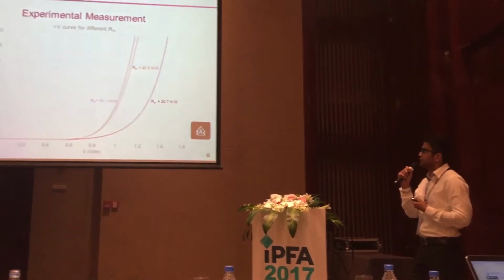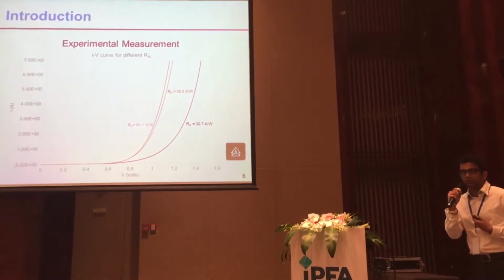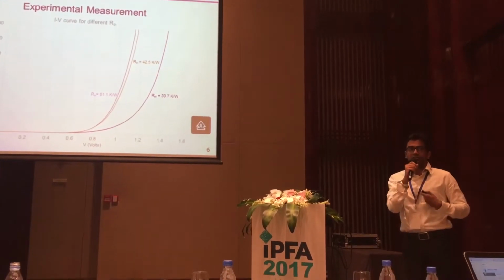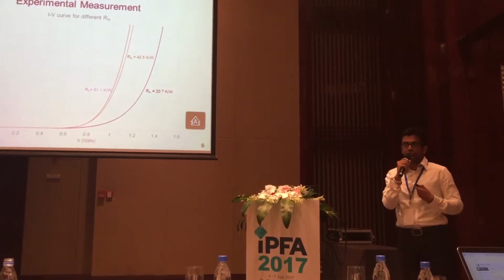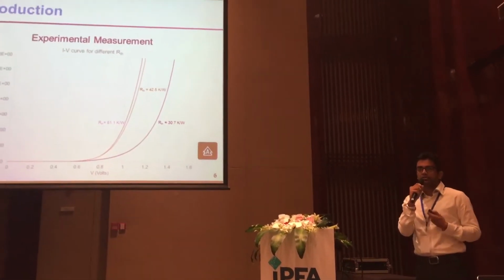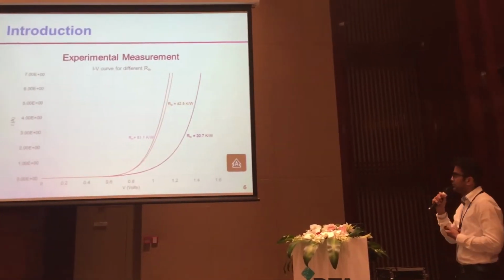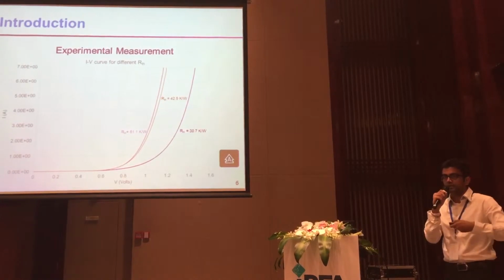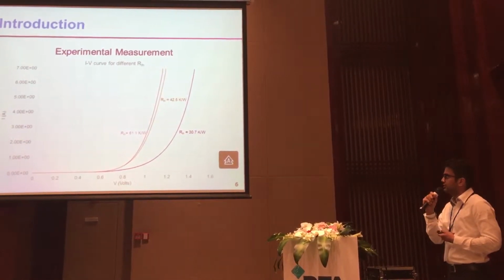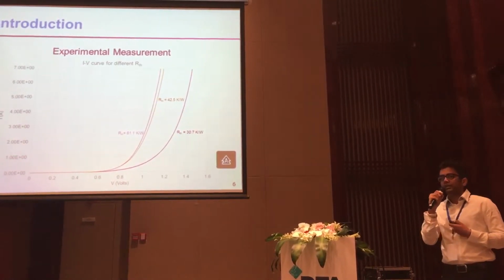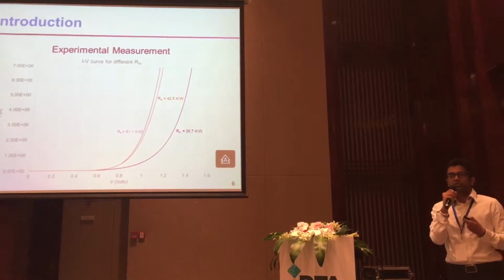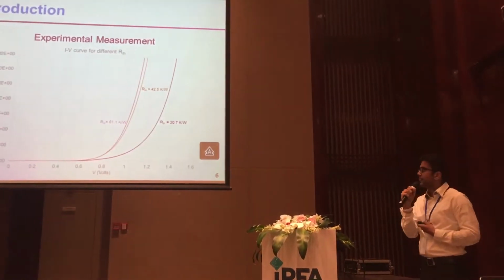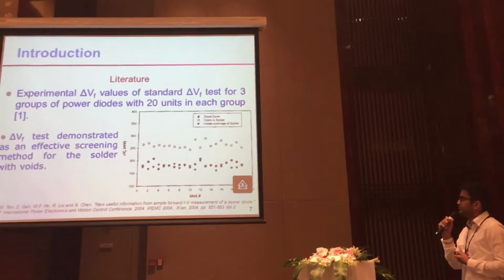For a similar kind of shift, we took some power diodes from a company, and we used a Mentor Graphics T3Ster machine to evaluate the thermal resistance of those power diodes. We also see that with a change in the thermal resistance of the complete power diode with the package, we can see a shift in the VF. So what we thought was, from the theory, there has to be a certain kind of relation between the Rth and the VF also. And this was the work done before, where